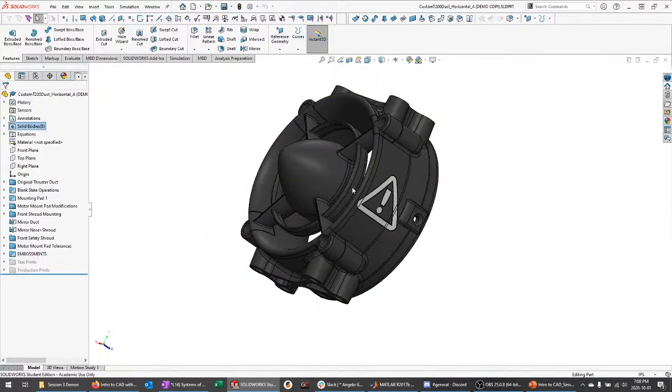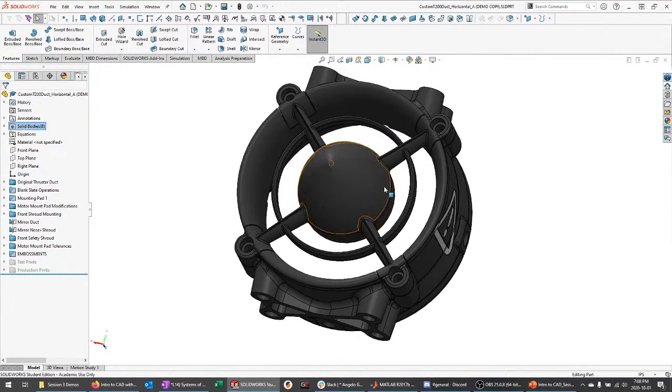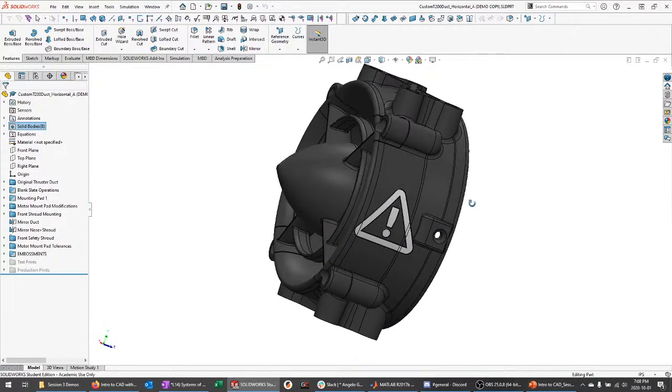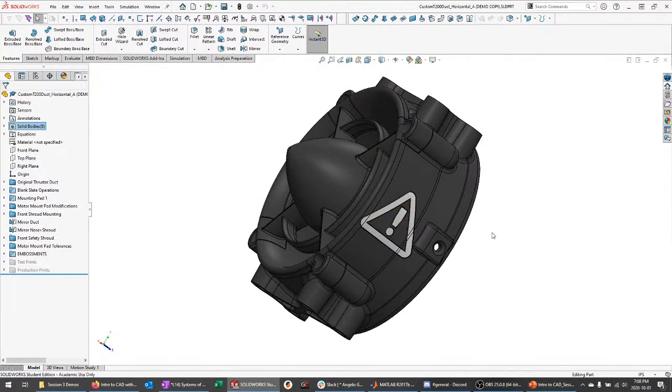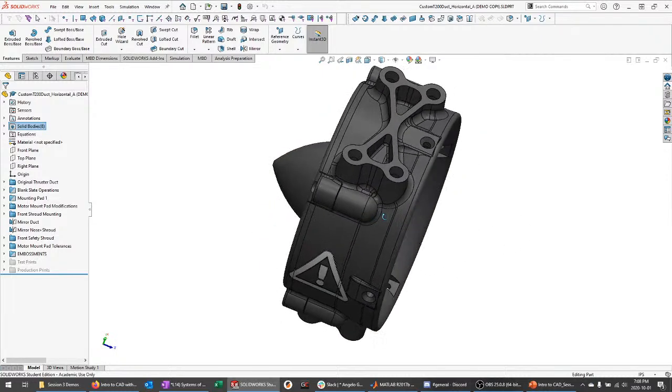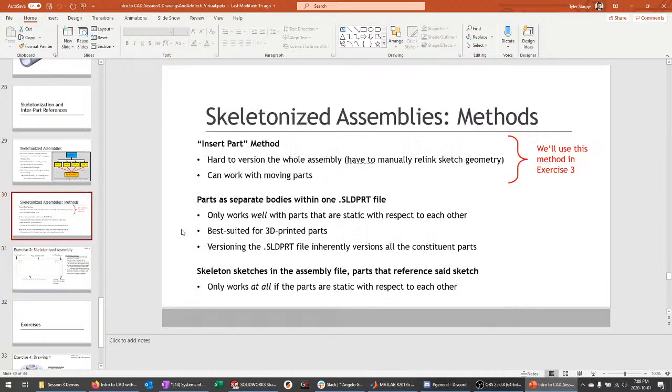In this case, I could have technically made a skeleton part and done everything we just went through in order to do this. You could technically do that, but it would be a real pain, particularly because this geometry is just much easier to create altogether and then split apart when you've got everything done. So there are advantages and disadvantages to all these different methods.